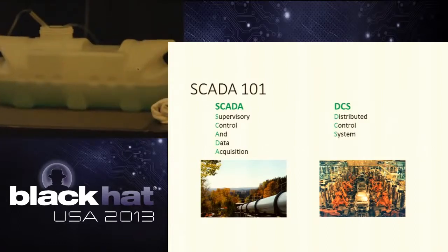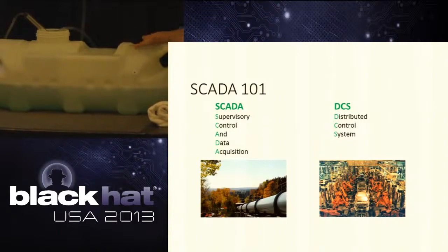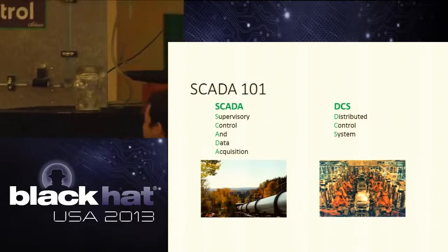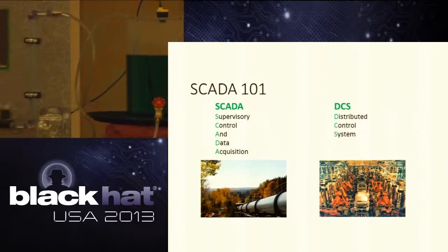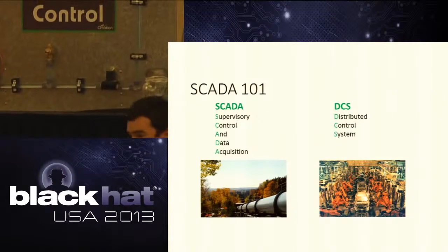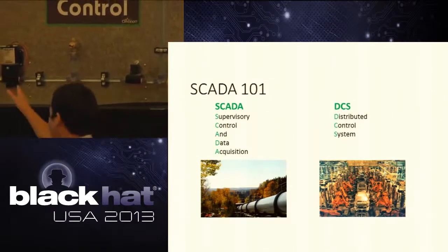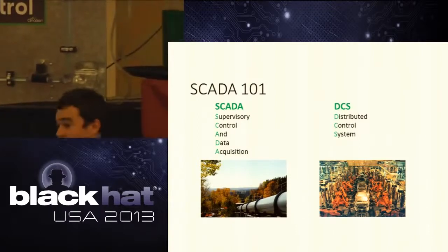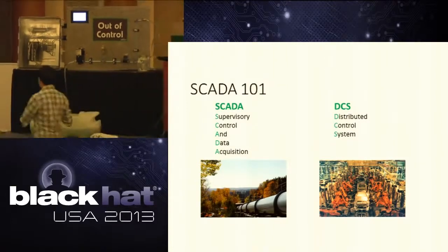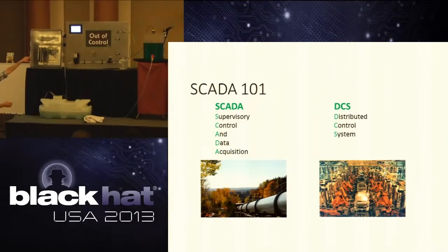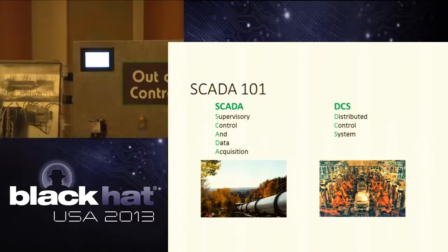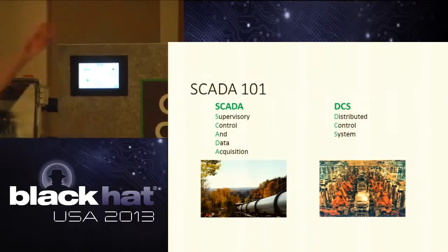Just to give you a brief overview of what we have: we have a simulated well itself. It goes up to a pump, then over into an isolation valve, and then up into our simulated tank. One thing that we also have here is this little brass guy, a pressure safety valve. You see those a lot in industry to prevent overpressures, but sometimes in production you'll have this pump and an isolation valve with no PSV in between. But we had to put one in just because we don't want to spray water everywhere. One other thing that we have up top is this little screen right here. That screen is called an HMI, and that's kind of the visualization of the process. And we can give you a quick show of what it looks like to actually work.